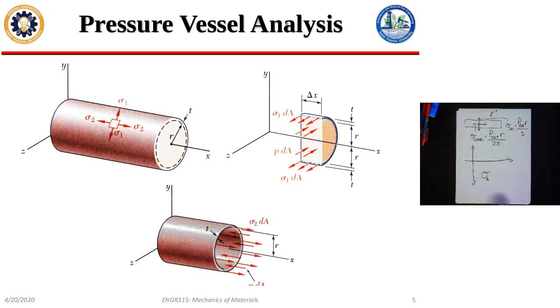No, Charles. Usually the average stress has been like sigma x plus sigma y over 2, right? So I have two stresses in perpendicular directions and in the same plane. That's like a sigma x and a sigma y, right? If I call this my x direction, this my y direction, I have a sigma x and a sigma y, and the average stress is the average of those two. So it's just the sum of them divided by 2.